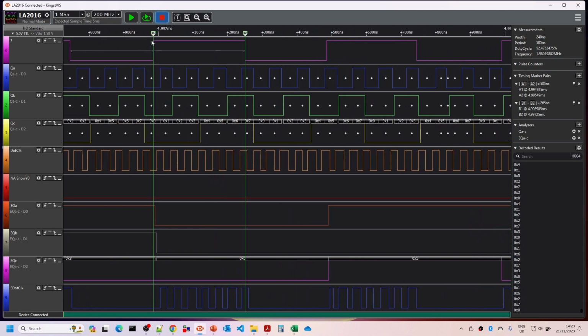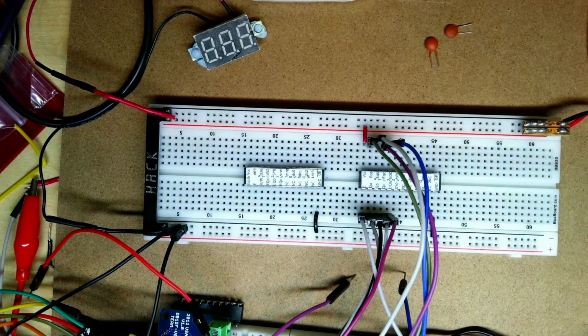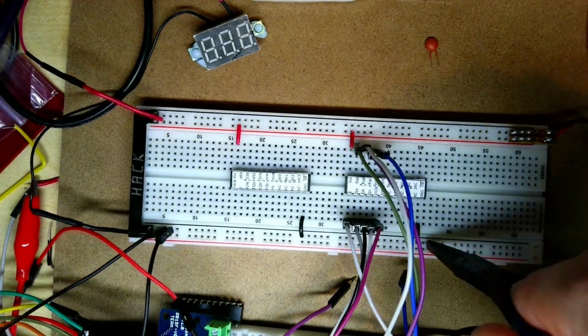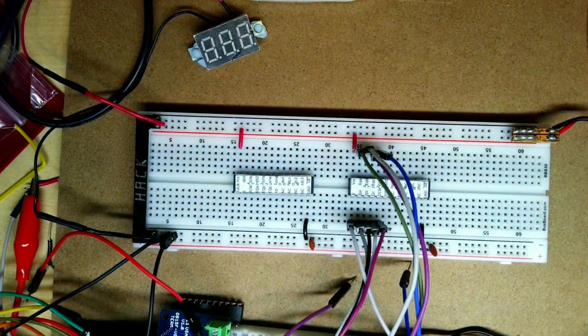So that's what we're going to look at in a minute. We're just going to wire that one up, and we're going to have to then wire some of the signals coming from the PLD that's just plugged into the top one. So what I'll do is probably speed that up as I wire it in, and then I'll commentate over it. Okay, so just connect up the power and put some decoupling capacitors in on the ground lines.